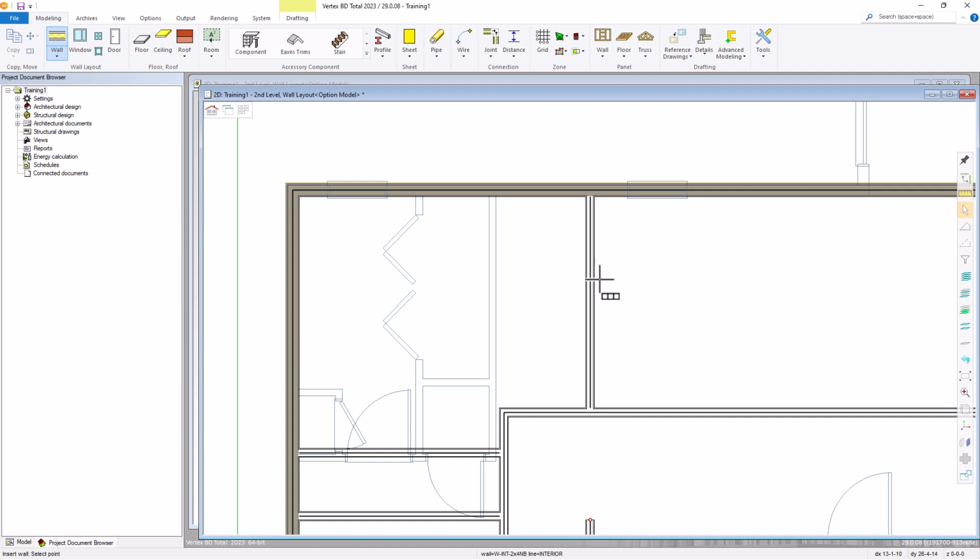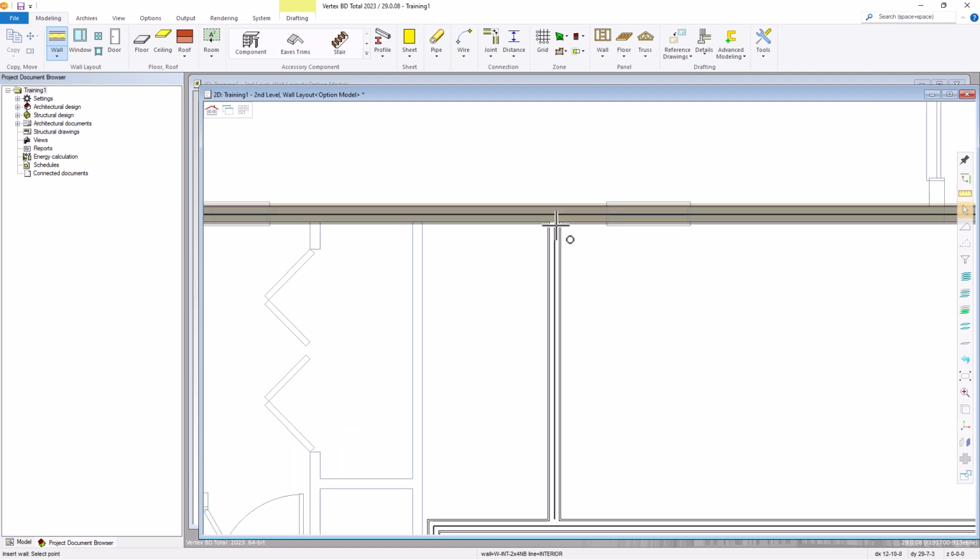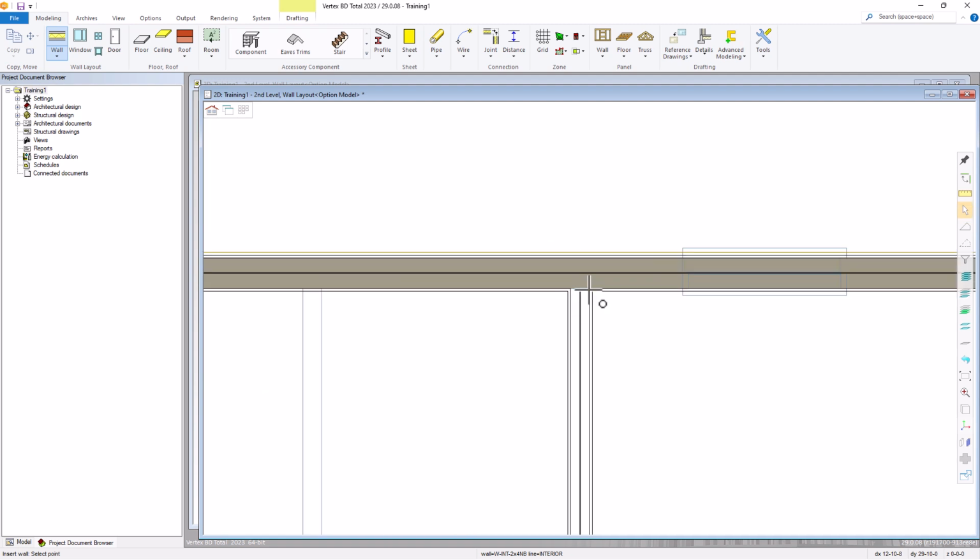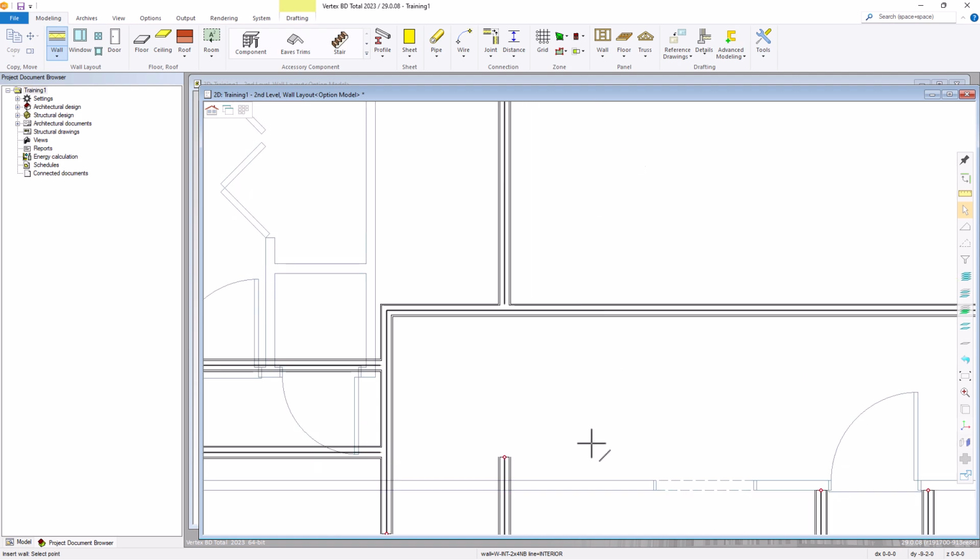And another closet, which is a 2 foot 4 inch interior closet dimension. So we'll Q off this interior corner. Make sure that we zoom in and get the framing. We have the yellow icon. Select the letter Q, U key, and 2 foot 4. And the wall should offset towards the right, which it is. So we'll lock it in the vertical and just come straight down to this wall.